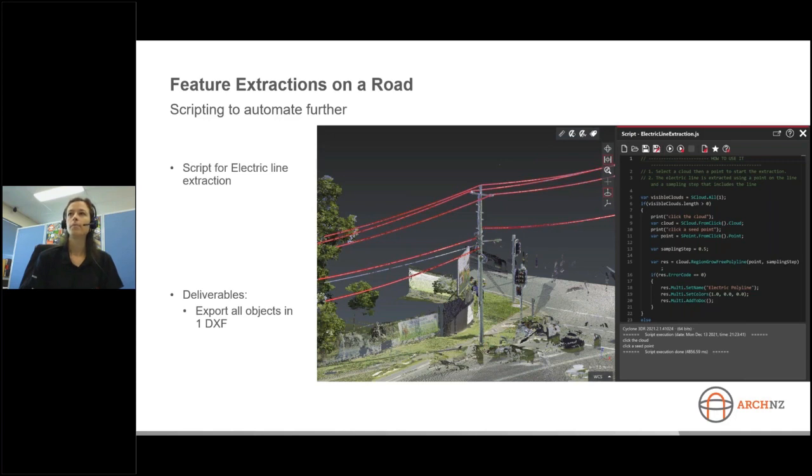Yeah, I think that's always a bit what's tricky with that function. It depends a bit what it looks like. If it's just a little area, I would probably try to still keep the main part of the terrain. Maybe erase that smaller part in there that has that quarry and all of that, and then just cut the quarry out of the point cloud and mesh it on its own, and then integrate it in the DTM afterwards. So you'd cut the DTM where the quarry is supposed to fit in, and then integrate that mesh in. So it's a little bit more manual. That's one thing I didn't show you during that presentation, but potentially I could do a quick video and send that to Lennon to upload on your platform as well.